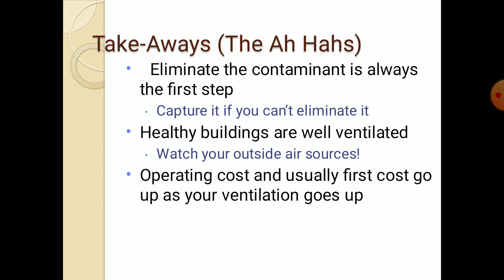So takeaway, eliminating the contaminant is always the first step. We have to capture it if we can't eliminate it. Healthy buildings are well ventilated with the help of this. Operating cost and usually first cost go up as our ventilation goes up.